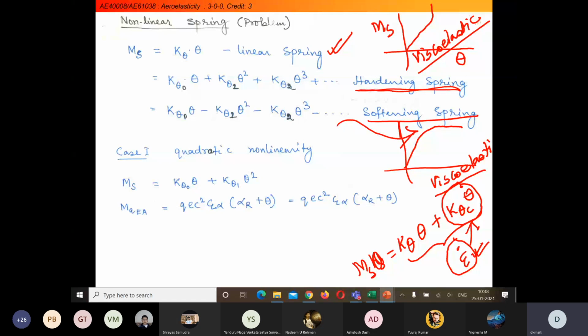In the structural stiffness, the force is proportional to displacement, whereas there the force rate will be equal to the strain rate. The F dot. So in normal structural behavior, F is related to x, and in the fluid we get F dot proportional to x dot.